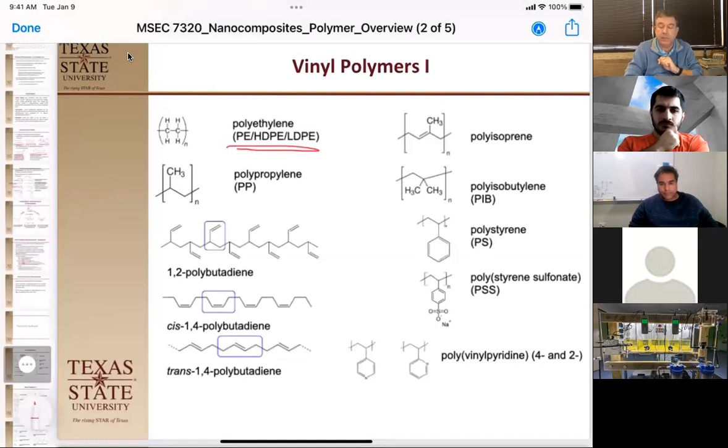Polypropylene can be processed a couple different ways. It can be opaque or clear. And because it's almost all hydrocarbons, it has very low surface energy. It's very hard to get some of the nanomaterials dispersed in polypropylene appropriately because there's no interfacial interaction between the polymer and the nanoparticle. So sometimes you'll see it's very hard to get it into polypropylene, but then they try something like nylon and it works great. So we should look at that as one of our systems. The polybutadienes right here, again, they all have different melting points, processing points, and different reactivities. So we'll see those all being used different ways.